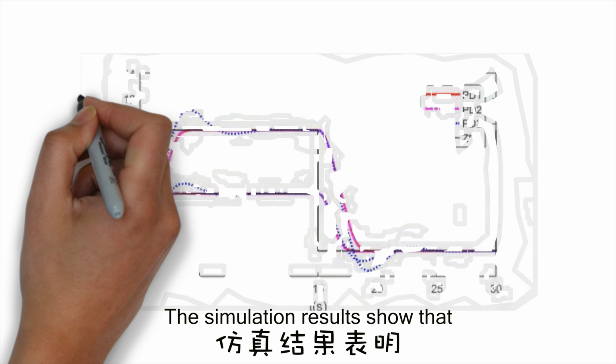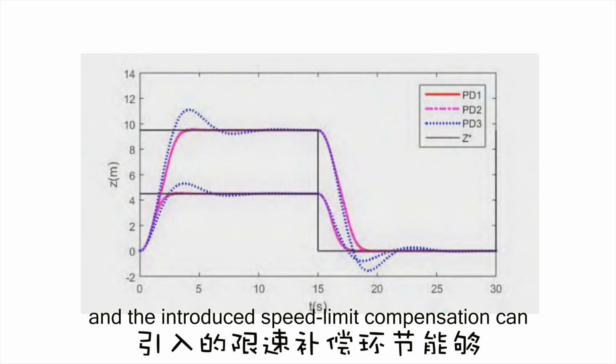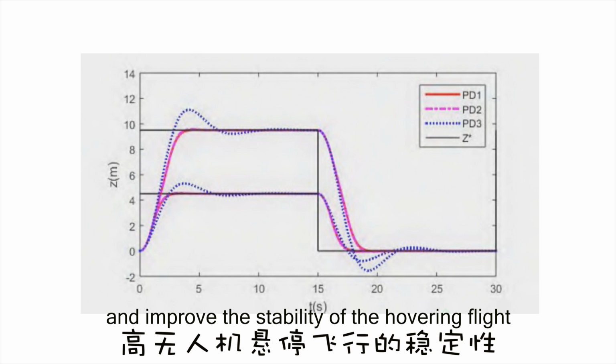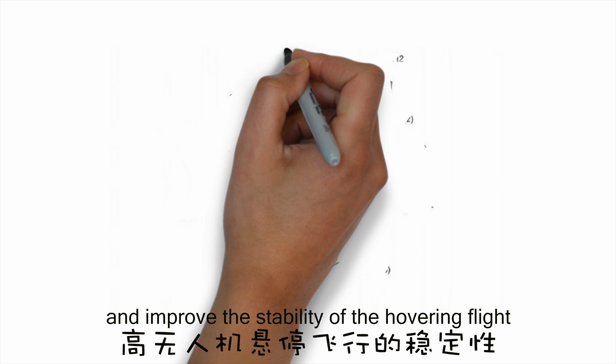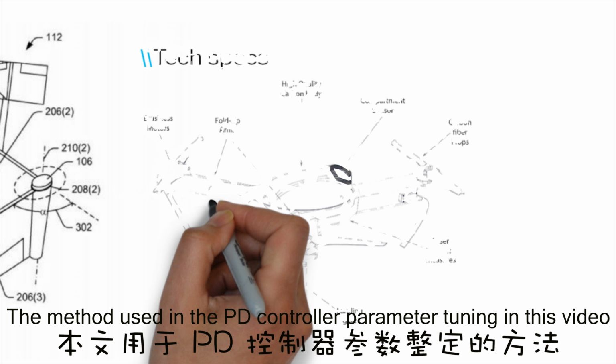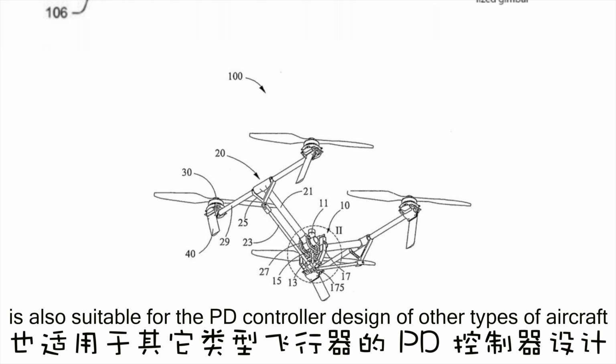The simulation results show that the designed PD controller has a good dynamic response, and the introduced speed limit compensation can effectively restrain overshooting and improve the stability of the hovering flight. The method used for controller parameter tuning in this video is also suitable for the PD controller design of other types of aircraft.